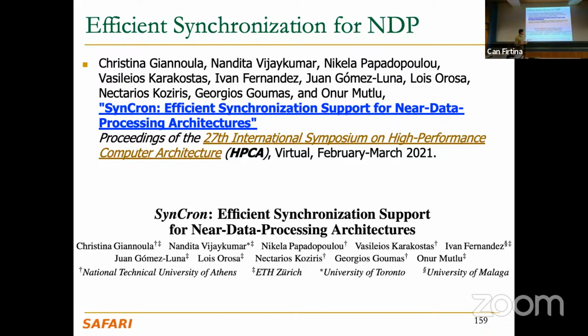So it's also important to do research in efficient synchronization techniques, efficient synchronization support for near-data processing architectures or processing-in-memory architectures, right? And maybe the ideas that you explore and start with are traditional synchronization mechanisms from other types of environments, for example multiprocessor systems, clusters, etc. Because in the end, it's going to be more or less the same, but at a different scale, right? For sure, you will have new challenges that you need to face and find specific solutions for, because the environment is completely different.